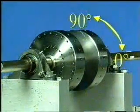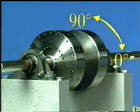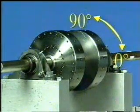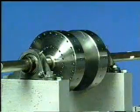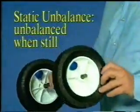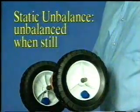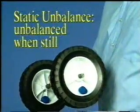Phase measurements from the horizontal to the vertical position at the same bearing location should shift 90 degrees, since the sensor is moved 90 degrees. These conditions are typical of a static unbalance condition. Static unbalance is a condition when the rotor is unbalanced, so that when it is at rest in a frictionless bearing, the heavy spot will swing to the bottom.